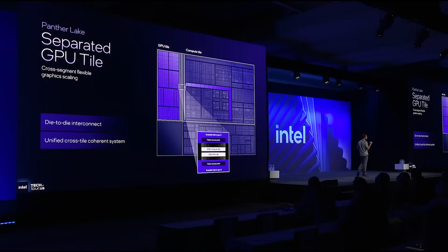Second, it uses one transactional protocol layer, which can be used within the tile or across tiles. This is what makes it partition agnostic. And third, it can carry multiple functional protocols, which makes it IP agnostic. These fundamental elements allow us to support a wide range of IPs and tile combinations.